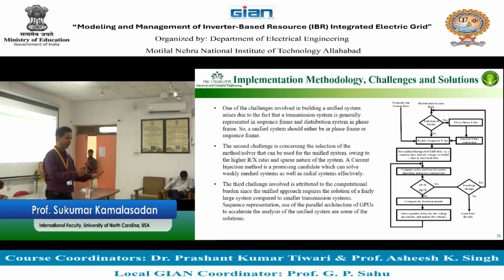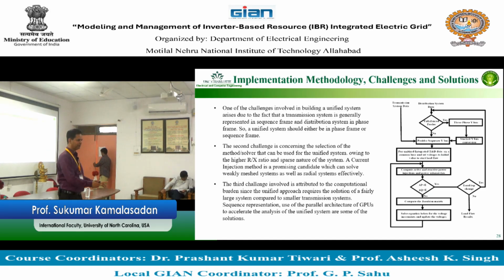At that time, it's balanced because the distribution system is completely balanced. Now, can you include negative sequence? Yes, you can. So what will you take care of for the unbalanced? You run a negative sequence correction, and that negative sequence correction will go with these corrected tie line Y bus points as a negative sequence. So unbalance comes into the picture with the negative sequence correction.